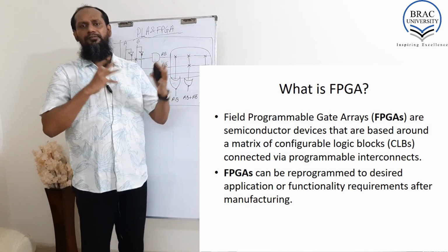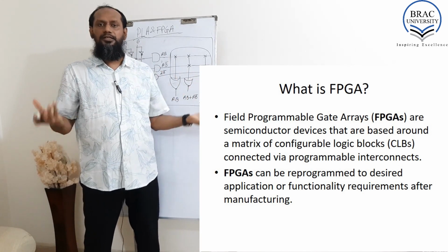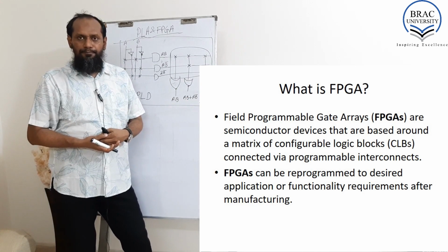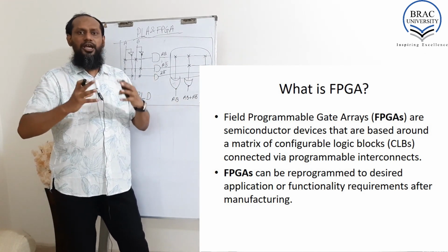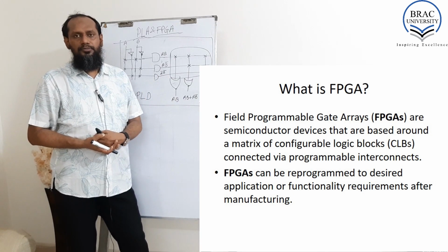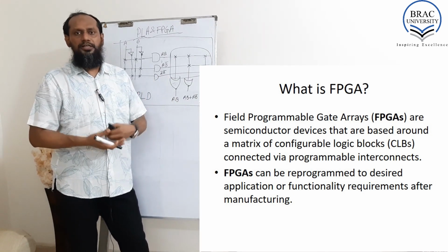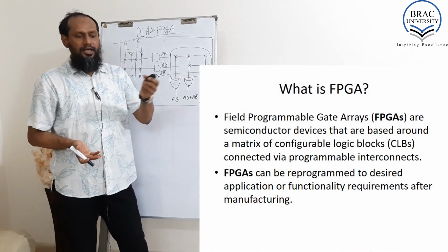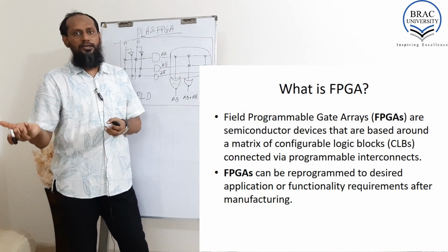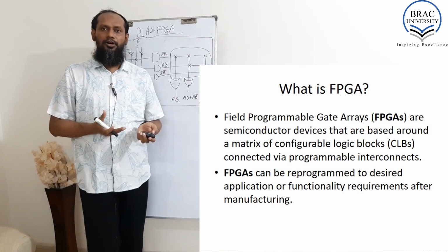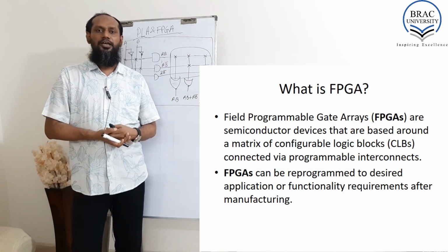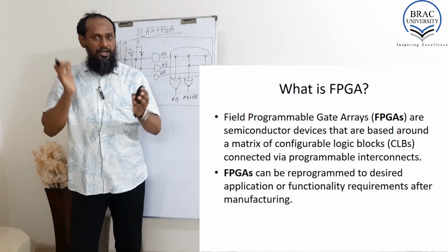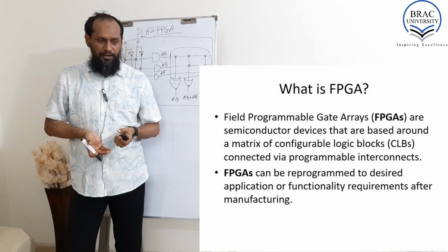So this is field programmable. That means we can change it. We can change the program. Like once we get a requirement from a user, but he wants some change on this hardware, on this logic circuit, we can do it. Okay, so that is why it is reprogrammable. We can change it, not like a PLA or PLD. PLD is one-time. Once we have programmed it, it cannot be changed. But for an FPGA, it can be changed.